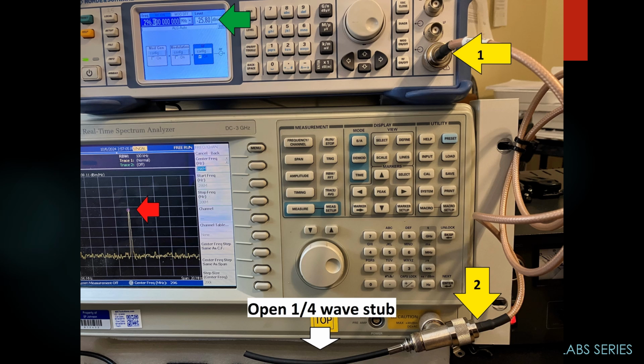So one more thing, you'll notice I actually cut my cable shorter than the math showed because the junction is actually at the yellow arrow, or the yellow line under the blue arrow on the right. So from that yellow line to the other yellow line, I made that distance equal to my calculation of 163 millimeters.